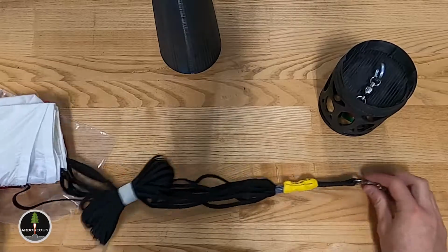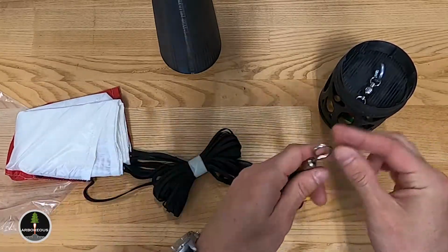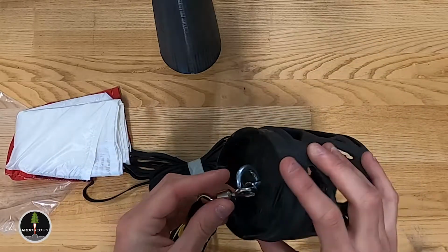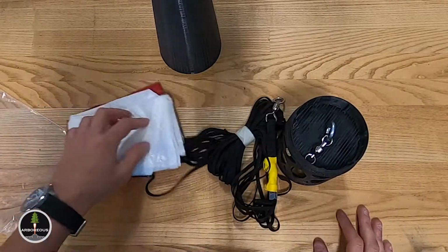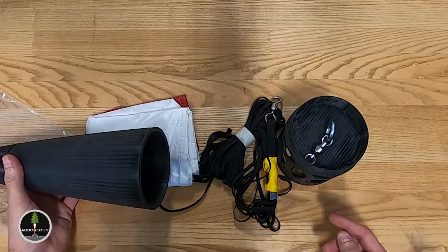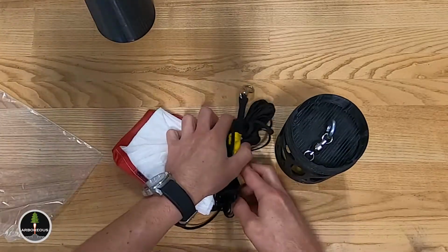Our case is a little different, as instead of bisecting our rocket and deploying from each end, we're going to have a singular deployment at the top near the nose cone for which our drogue and main would both deploy. And our main parachute will stay furled thanks to our electronic chute tie that will release at a predisposed altitude.